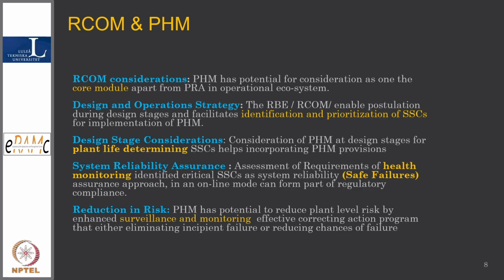Now, we are talking about the systems approach where PRA is there, but PRA has given input to the risk-based approach, and a spin-off is risk-conscious operation management, the application of the risk-based approach into operation and maintenance. So how can we see RCOM and PHM in perspective? RCOM consideration is related to after PRA, and it has a direct relevance, because present maintenance strategies are schedule based. So when the schedule has arrived or the replacement time has come, we replace it, either prematurely or on time; we don't know actually.